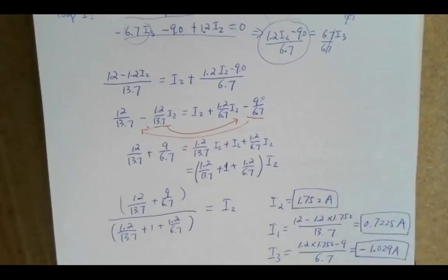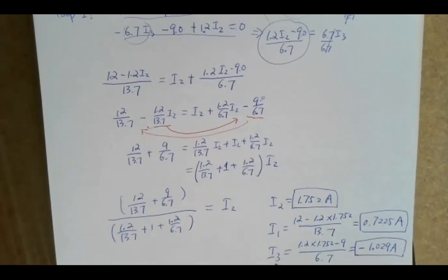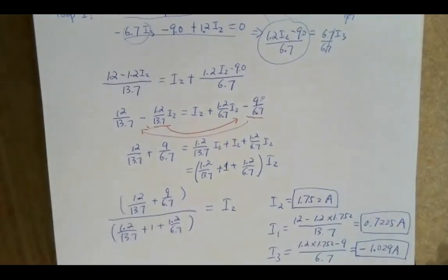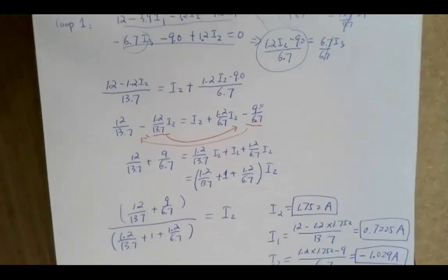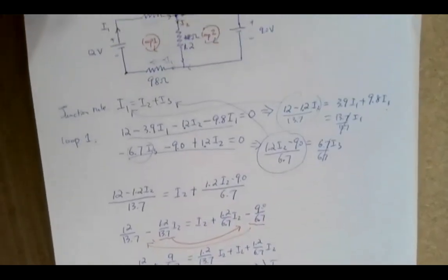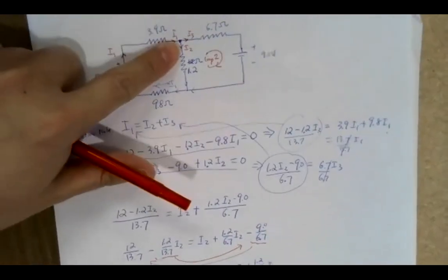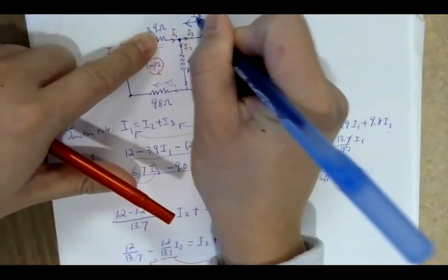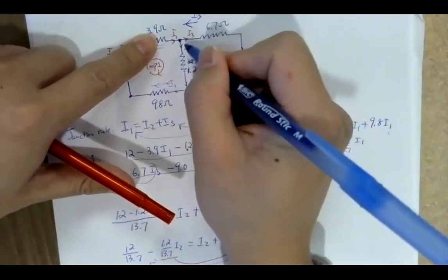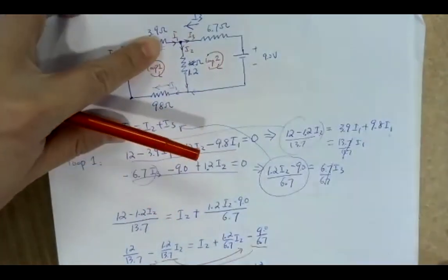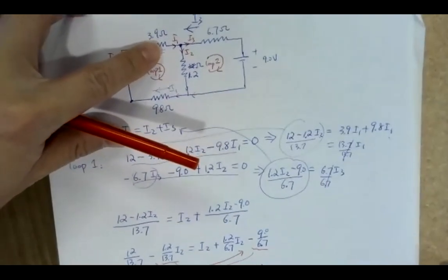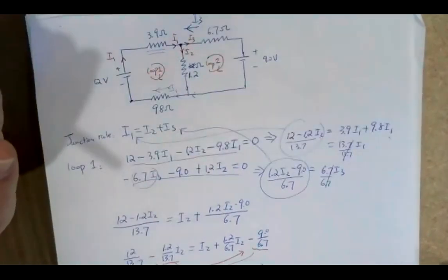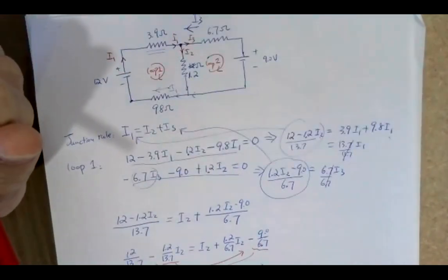All right. So I3 is minus. I1 and I2 are positive. I3 is minus. So that actually tells you that your initial assumption for the direction of I3 is not correct. So indeed, your I3 will be in that direction. That will be your I3 direction. So I1 and I3 go in and become I2. That's basically what it says. Your direction of I1 and I2 are still fine, but I3 is not. It's in the opposite direction. So when you get a negative sign, that's what it means.